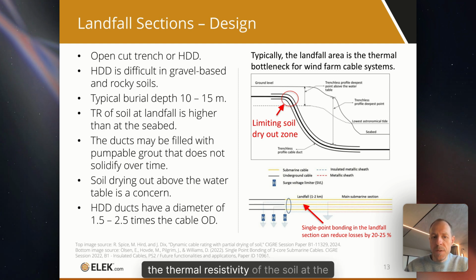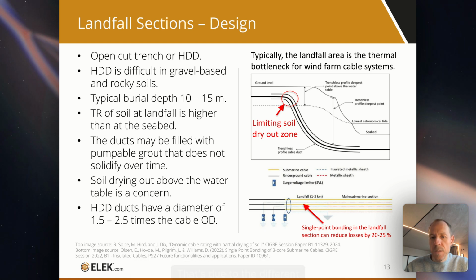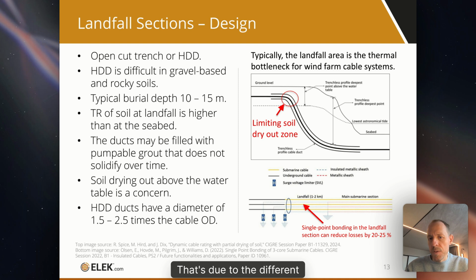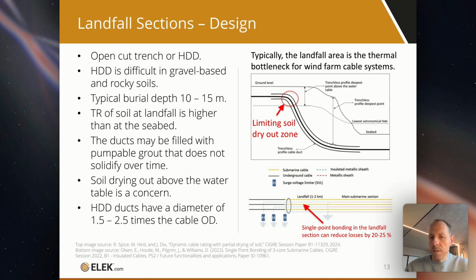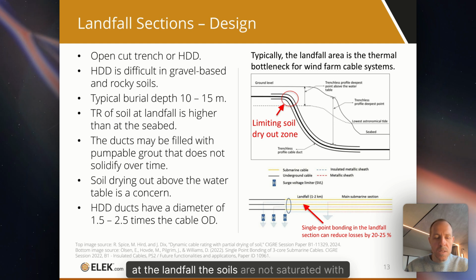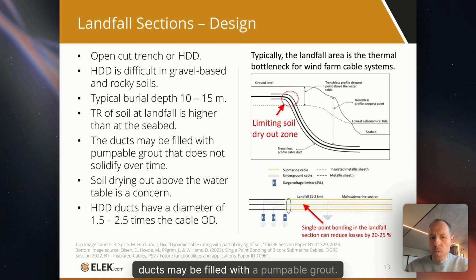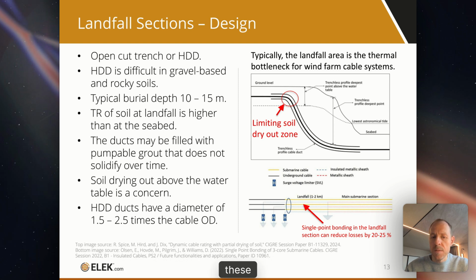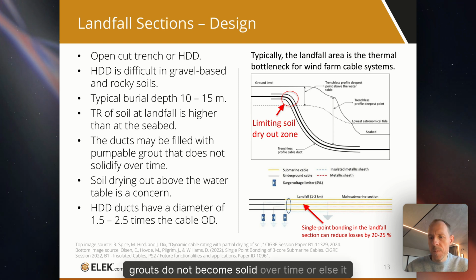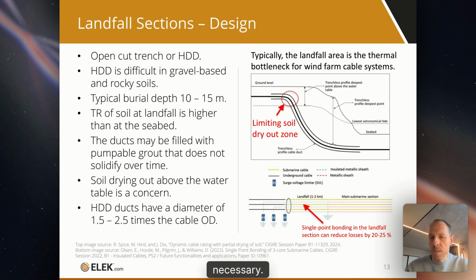The thermal resistivity of the soil at the landfall is higher than at the seabed. That's due to the different soil structures, but also because at the landfall, the soils are not saturated with water. The ducts may be filled with a pumpable grout, and it's recommended that if that's done, these grouts do not become solid over time, or else it will be impossible to retrieve the cable if necessary.